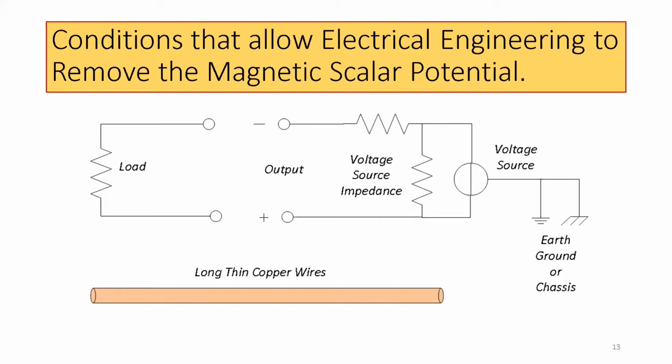You're not going to see longitudinal field components in a long, thin wire as compared to the cross product components, because the area around the wire is so much greater than the area looking in the ends of the wire. So usually when you have a long, thin wire, the difference is thousands of times. So you virtually can ignore any scalar effects in normal electronics.